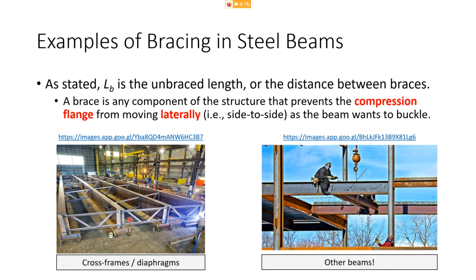And in between those, you should see these little truss-looking things. They look like there are horizontal elements, and then they look like they've got a letter V in between them. Those elements are intended to prevent the beams from buckling at that point. At that point, they're preventing the beams from moving laterally.